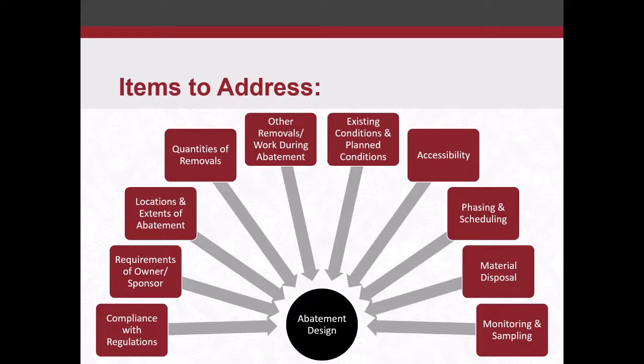Material disposal. There's standard stuff for your friable asbestos waste. There's standard protocol for your PCB waste as hazardous materials, mercury as hazardous materials, lead-based paint, testing and characterizing it. So we want to make everyone aware of what needs to be done with that process, and there are time frames that you can have certain waste on site, so make sure people are aware of that, so you're getting the waste off site in the appropriate time frame.